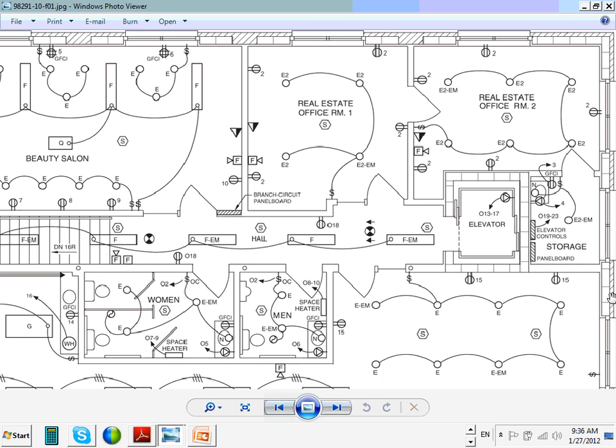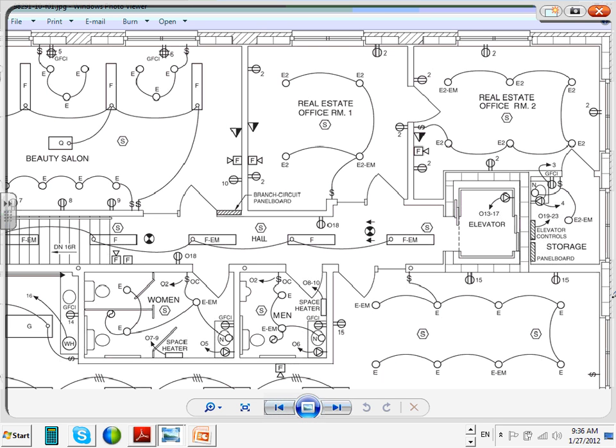Do you guys remember these two where they placed the emergency lighting fixture? Can I have you guys for 1 second? You're in the insurance office and they want you to be able to get out. So I'm just going to draw a line and show you the traffic. Look how they put one here and they put one here and they put one here. That's what they call it, the egress path out of this office. What is an egress path? That you're going to dedicate a path of 2 feet or 4 feet and get the people safely out of the room.